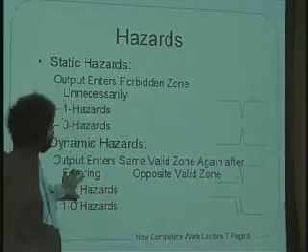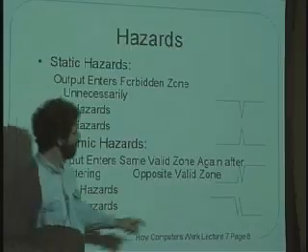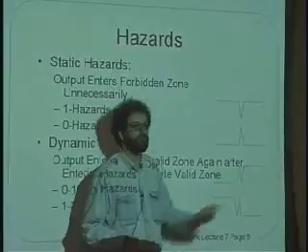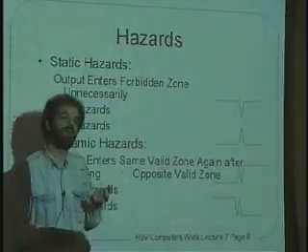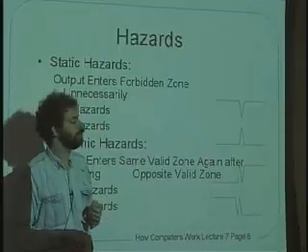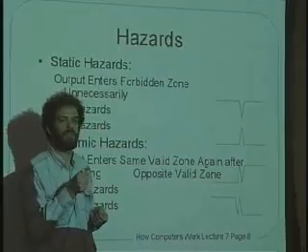And there's also other kind of hazards which are called 0-1 or 1-0 hazards that look like this and involves a kind of a hesitancy in terms of making a transition between a 0 and a 1 where it sort of bounces up and down a few times. Many of you have, of course, had experience with pressing the set buttons on a clock.